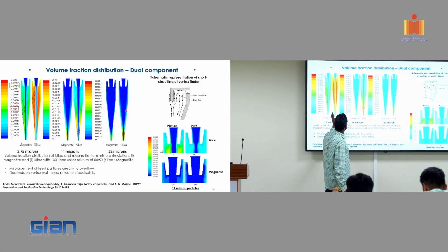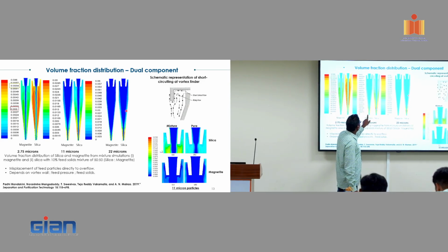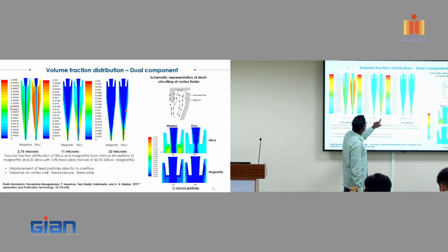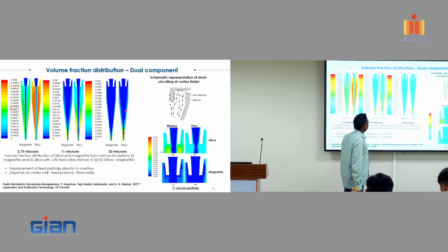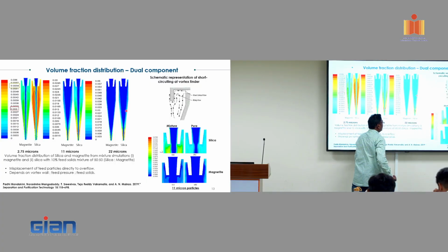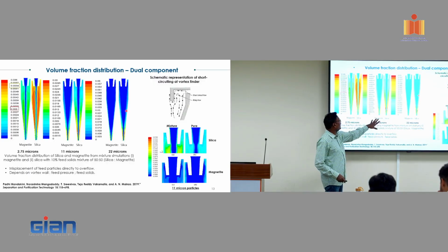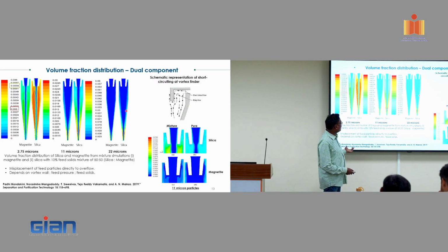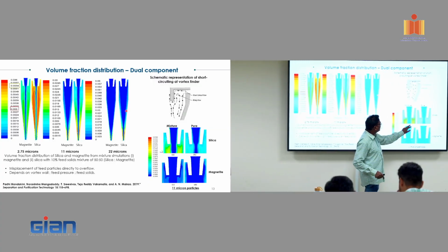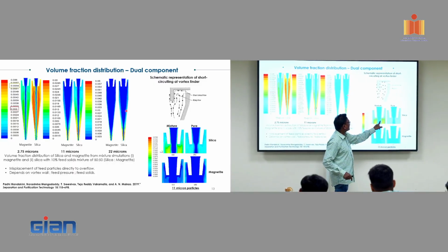So then you can see when you look at the silica 11 micron, in case of the magnetite, it is actually going downward, and 11 micron silica goes up, but 22 micron silica is also, some of them are coming in the downward form because the size cut density is about 11 micron. Now when you go for the changeover here, you can see now some of the particles, the earlier they were reporting here, but now you can see they are actually getting reduced.